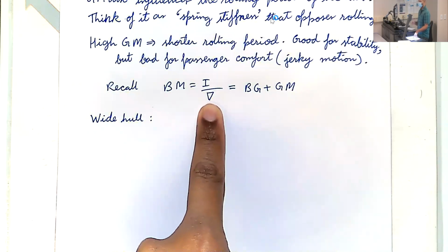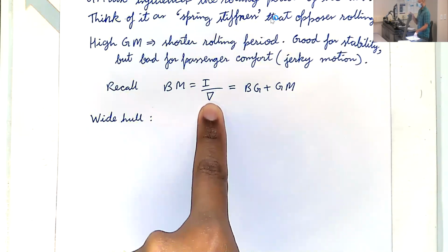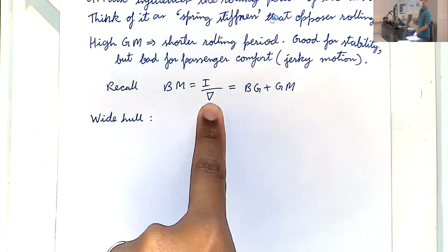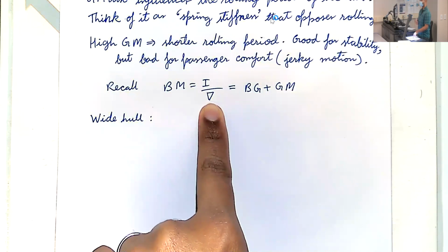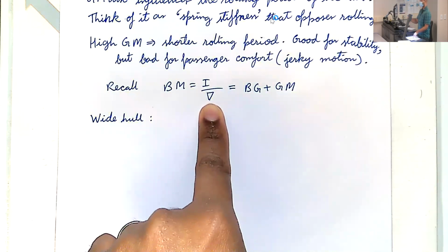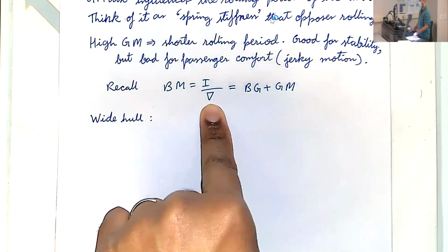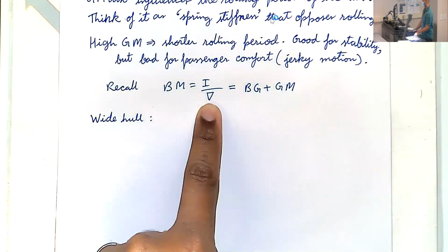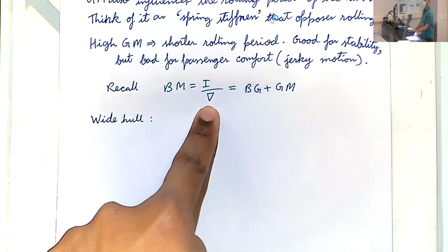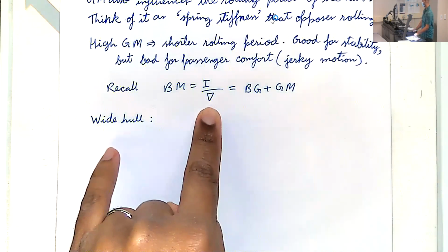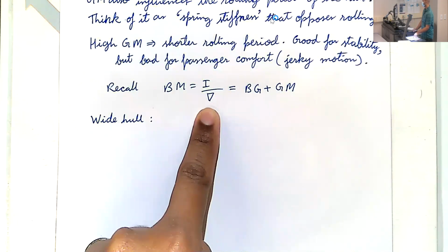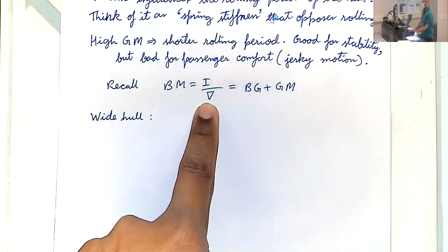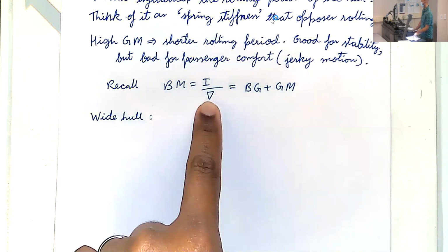If I don't tell you the geometry of the ship and ask you how much volume of water it is displacing, what is the one number you need? The weight, yeah? So the weight determines the submerged volume, nothing else. Not the geometry, not the distribution. If I make you widen your hull, it has no influence on nabla, okay?